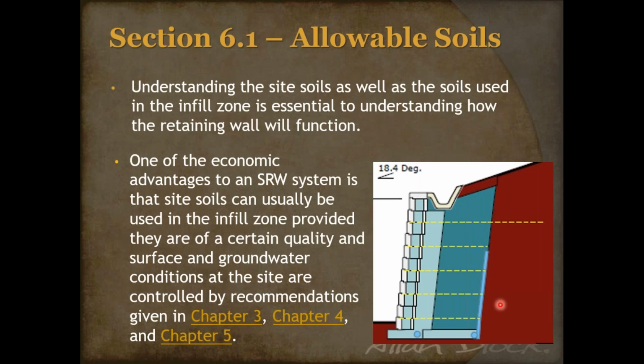More often, site soils have that clay content, and are less likely to change their properties when they maintain their optimum moisture condition. We do have a question that says, talk about the plasticity index change in response to rain events, and how do you deal with that? Rick, this is exactly timely. You try to prevent it. You try to minimize how much water is being introduced to the soils. So that's where these blanket, chimney, and swales, all of these are being added to the system to keep your soils here as optimum as possible. And so we'll continue to elaborate on that as we go through this as well.